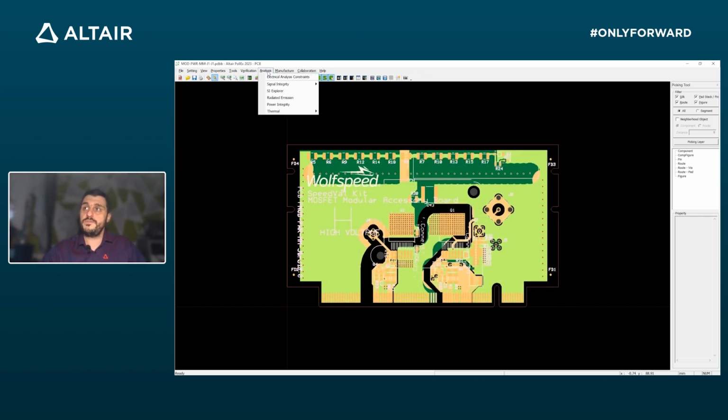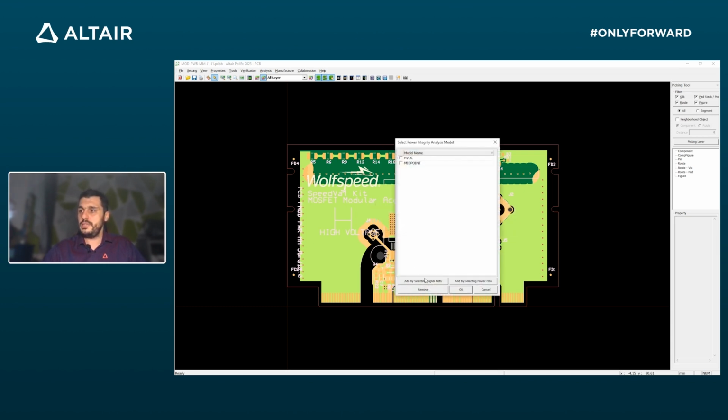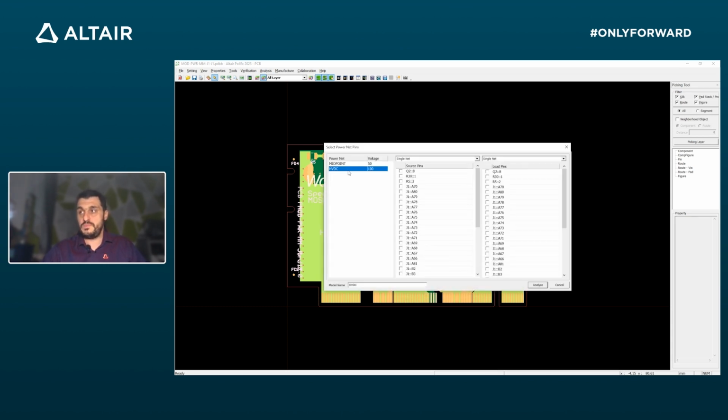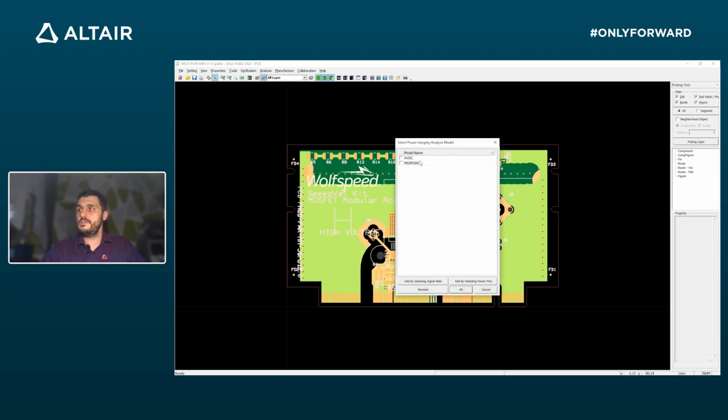And then we can easily perform a power integrity analysis, just running the power integrity tool, selecting the node which we want to analyze, the source and the sink, so the device that is collecting the current. I would not overwrite it because I want to save some time, so I will show you how it looks in the system for the simulation.